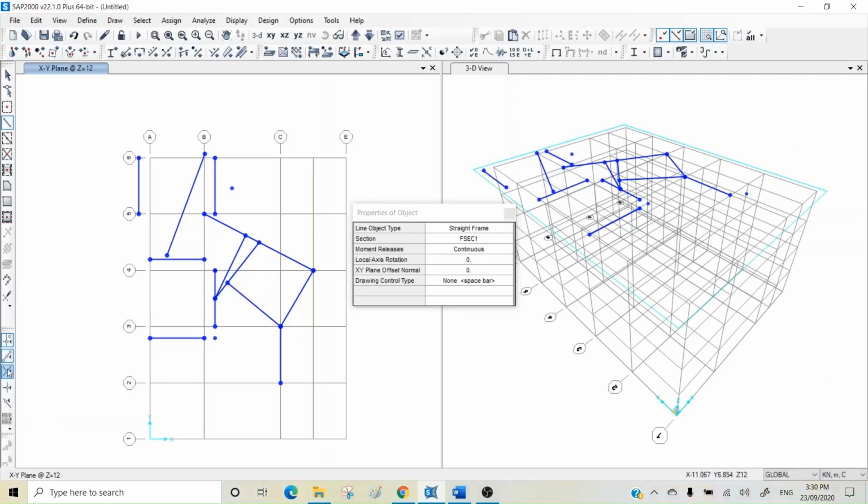And for example, select intersection. And when you're coming to intersection, you can see currently we don't have any intersected members, so I'll show you. But using whatever snap is activated here, for example, if you remove midpoint here, you cannot choose midpoint again. You have just intersection between the grid and frame or between frames. So I'm coming, for example, selecting this. If you draw an element just crossing the other element like this, that is another intersection for you. So you can pick that one as well.